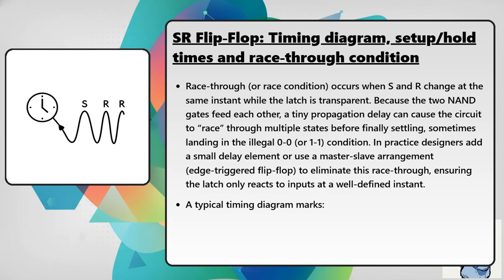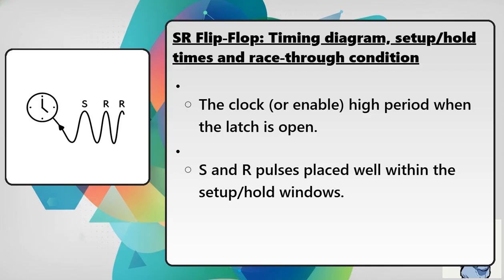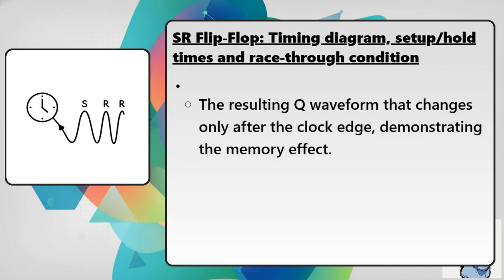A typical timing diagram marks the clock or enable high period when the latch is open, with S and R pulses placed well within the setup and hold windows. The resulting Q waveform changes only after the clock edge, demonstrating the memory effect.